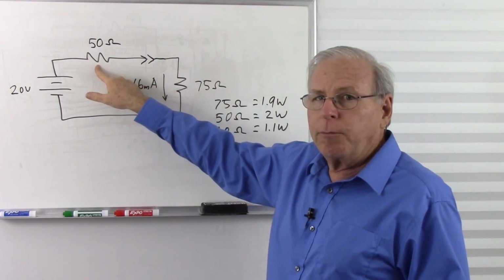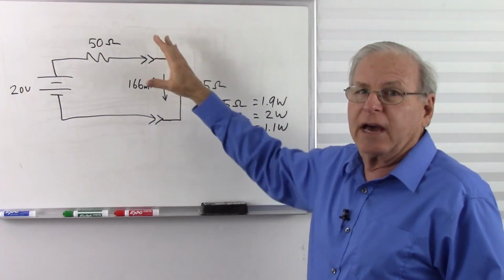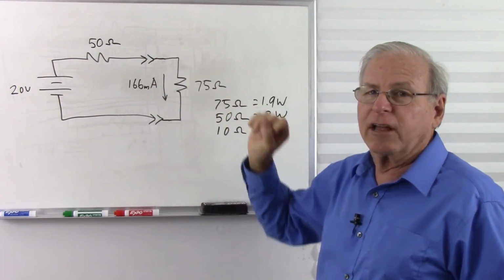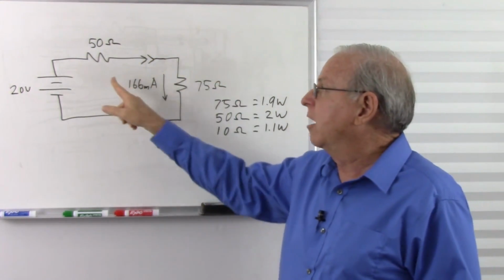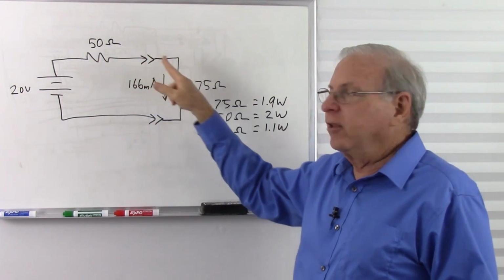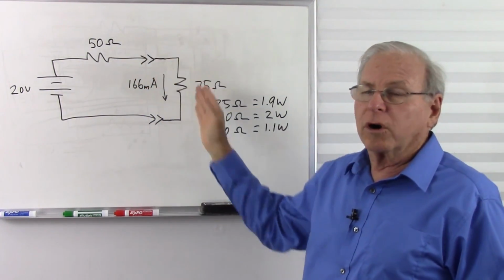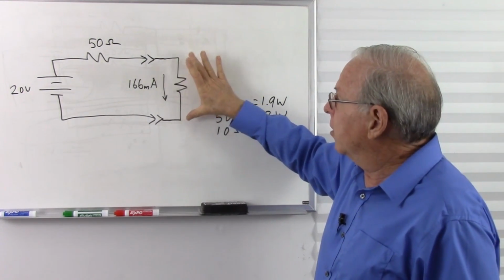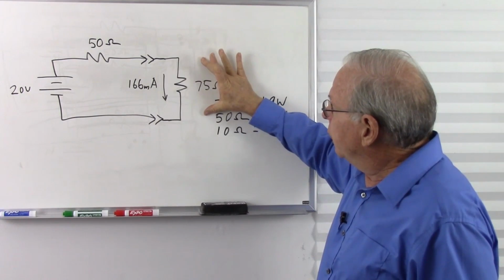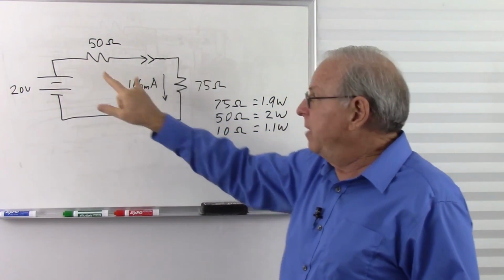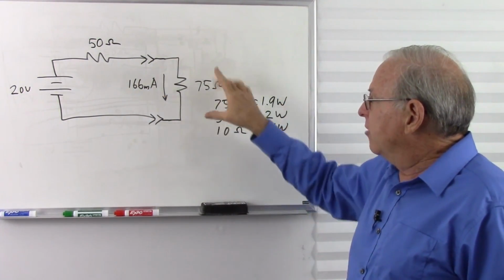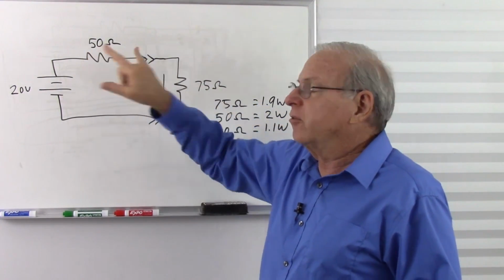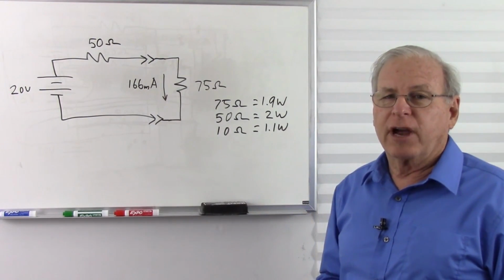But if we have a high output impedance and a low input impedance, we have a voltage drop and we have a significant loss in the voltage. So that's usually undesirable. So the one thing that's undesirable is to have a high output impedance and a low input impedance. They don't work well together. And finally, if we want to maximize the power, develop the most power across our load, we want the load impedance to match the output impedance, as I showed here. We get our maximum power across our input impedance if it matches the output impedance of the circuit driving it.